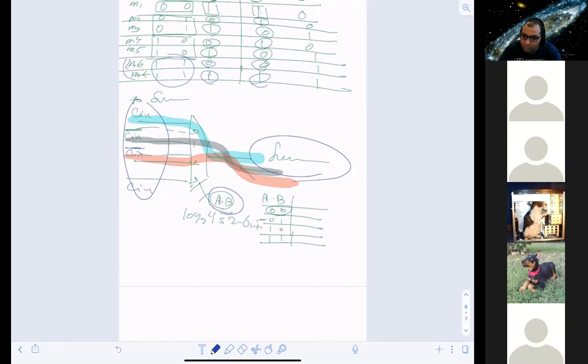So can we reduce it to a 2x1 multiplexer? You can do whatever you want. It's not very hard. You can add more gates, right? Because the rest will be something going in input, right? Have you noticed when I made it 4, 1, I just use a wire here, right? Wire, invert. But if you're gonna make it 2, 1, then the other 2 variables have to go into the wires, right? You understand what I'm saying? So instead of 1, it's gonna be 2 of them going inside, right? Yeah, that's right. So you're gonna add more gates. That's the compromise here, right?